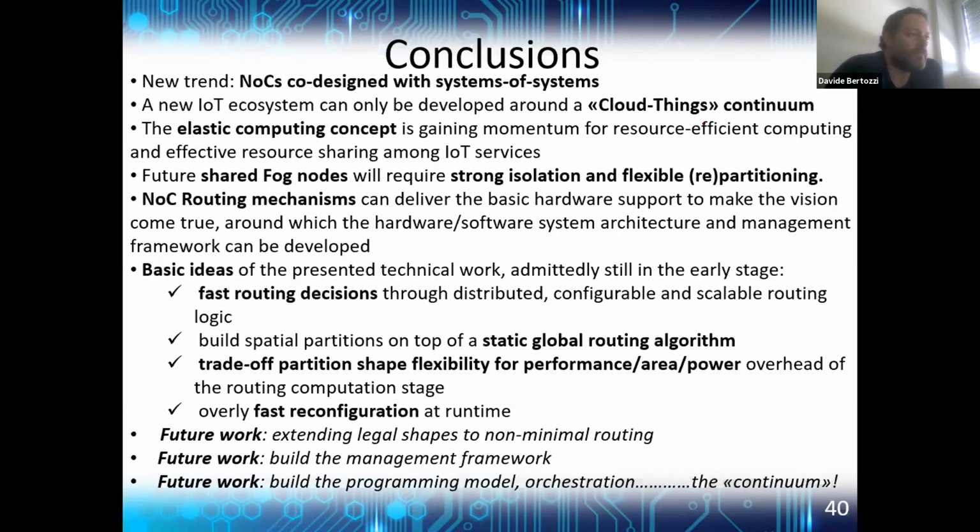Okay, so a different approach that I personally prefer more, that I explored in the past, some papers on that if you're interested, was to implement the network on a chip as an independent voltage and frequency island. In this case, you have decoupling of the operating condition only at the boundary. You can put 2 clock FIFOs at the boundary of the on-chip interconnection network. And since having such a widely distributed domain is challenging in terms of the clock distribution, then you can think of mesochronous synchronization. So you can relax the constraints for distributing your clocks throughout the switches of the network.